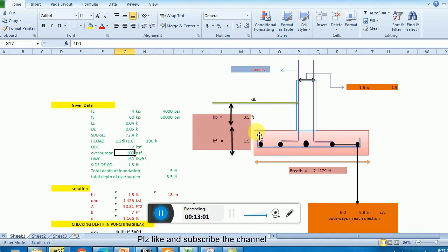Remember, the total depth from the ground level to the bottom is assumed to be 4 feet. As we don't know the thickness of the footing, we are using the average density of the soil and concrete. That's why I am ignoring this overburden and using 0. The unit weight is the average unit weight, so 125.